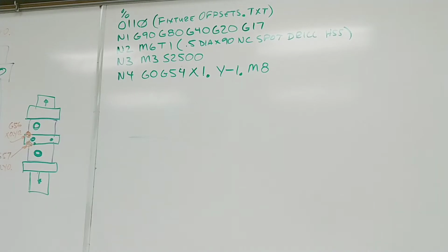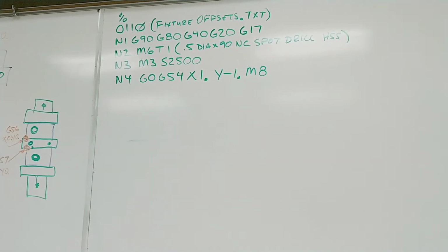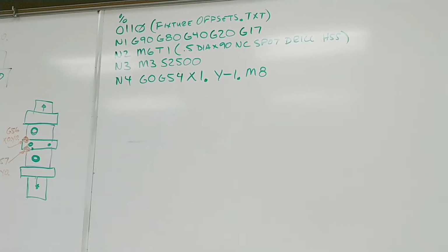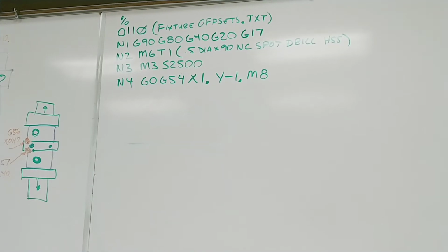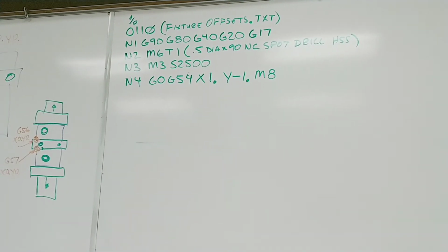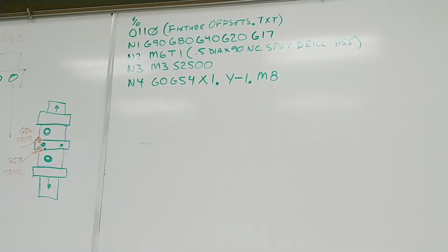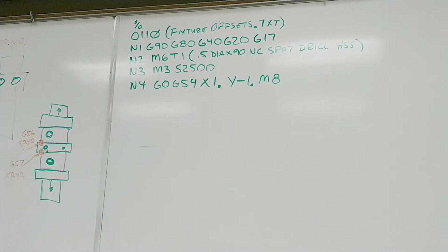We could even, if we had a setup, set up calipers and inspection measuring tools. You could even measure it that way. It would not be practical, because the machines have servo motors, they count out their displays. You can always use the machine to make that measurement, and that's always the most precise way to do it.